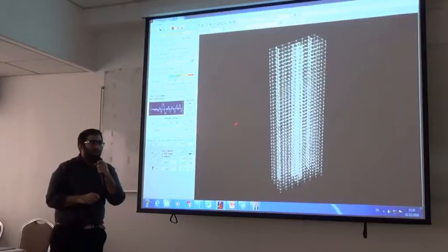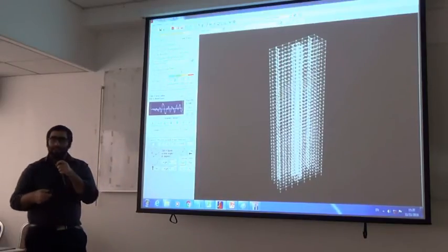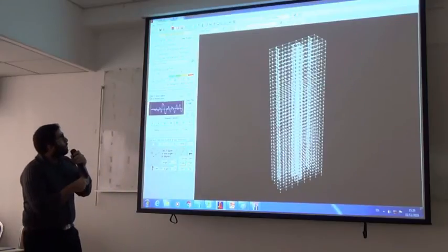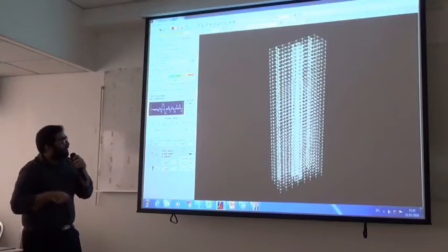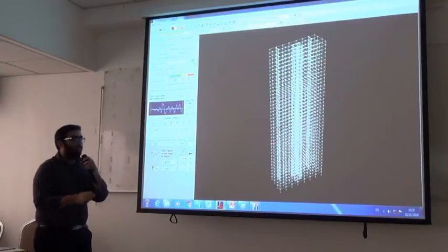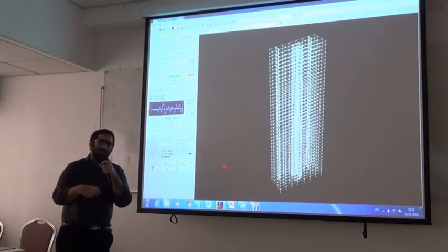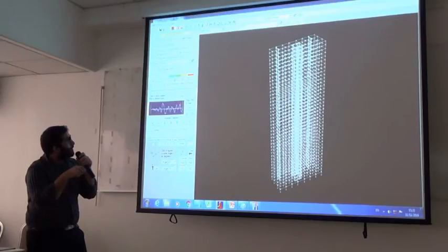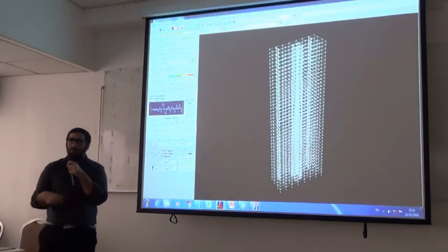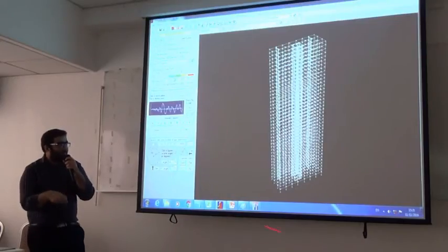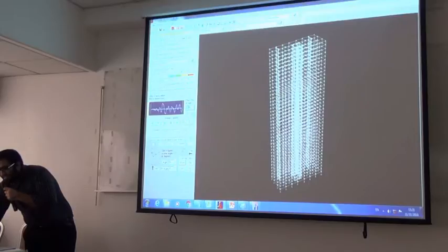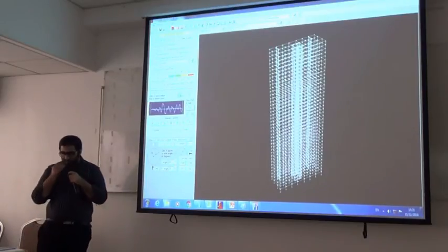If you remember, yesterday I spoke about the hinges being rigid plastic. Basically, the hinge will not have any rotation if the moment is not exceeding the capacity. That's why I put a very low number for the rotation over here, just to show you that if there is a little bit of rotation, the DC ratio will be 0.01, and then you can have some color forming over here corresponding to the fact that the beam has started to yield, right? And then you can have some other colors also. The DC ratio of 1 basically will mean that the deformation capacity assigned to the hinge has been exceeded. If you remember the numbers that I used, some typical numbers like 0.025, something like that will be exceeded, right? So I will plot this one for you over here. Okay, we need to give it some time to plot, and then you can see some colors also.